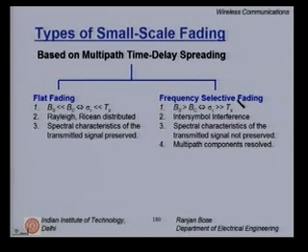Usually, it is unfair to comment without the knowledge of both the signal duration and the delay spread, whether the channel is frequency flat or frequency selective. However, in the case of UWB communication, even if you go into the room environment, you tend to encounter frequency selective fading because of the large bandwidth for the ultra wideband scenario.